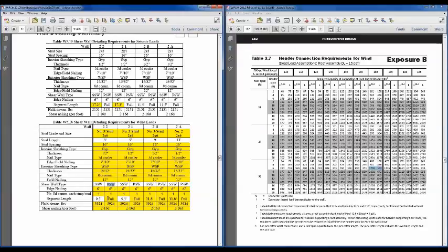For the segmented shear wall, it's again the seismic that controlled for this particular wall, but you're going to fully sheathe the perforated shear wall. The hold down requirements are very similar, and then that shear nailing at the bottom of the wall, nailing to the floor system, is 2 16-penny nails per foot from table 1.